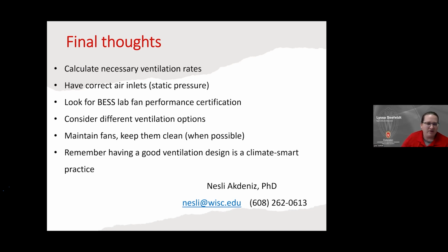What's going on there? So static pressure is the resistance to flow. If static pressure is high, let's say we have a very small air inlet that is not designed correctly, then static pressure will be above 0.2, right? Then it's so difficult to pull air. So the fan will be working very hard, but it will not be able to draw the air through the barn. So the efficiency will go down, and we will spend more energy to draw the same amount of air through the barn.